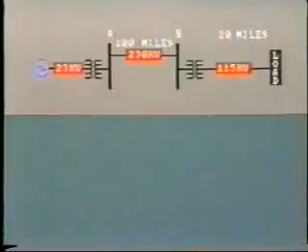In this section, we'll look at the convenience of using the per unit system. Please note, however, we're not dealing with the complex subject of fault analysis. For example, in this simple system, the 220 MVA generator supplies the load at bus B by feeding power through the two transformers and the connecting transmission lines. Note that we have several different voltage levels. 23 kV at the generator terminals, 230 kV along this transmission line, and 115 kV to the load.